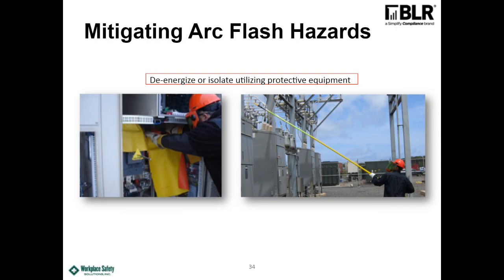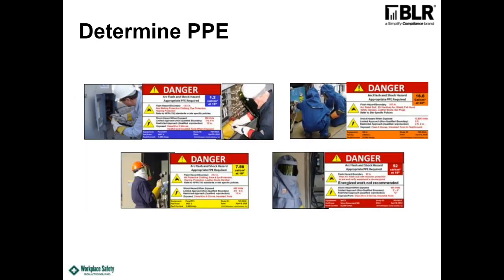So de-energizing, and so again, you're testing and working and doing whatever you need to do with a hot stick. That's one way of mitigating. And on the left, there's a shock hazard with 480 volts and 950 volt DC and all kinds of stuff in this inverter cabinet. And so that's just covering it up to minimize your risks to be able to go into the control cabinet above. So there's a lot of different ways you can do safe work practices.